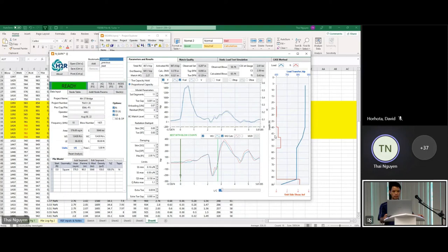If you have a blow count higher than the observed, that would mean your future driving criteria is going to be a little bit more conservative as well. Let's stay with blow count match level 5 for now to see what happens with F4.